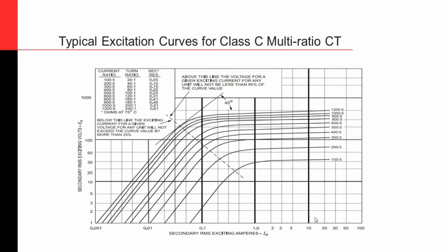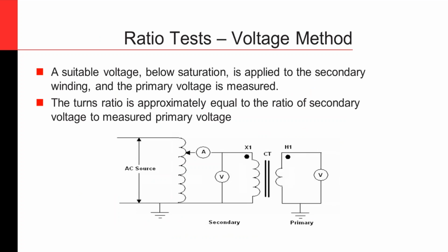So that's the saturation test. You apply voltage and you measure the current on the secondary on each and every single tap. So this is your response. This is your typical response on each and every single tap.